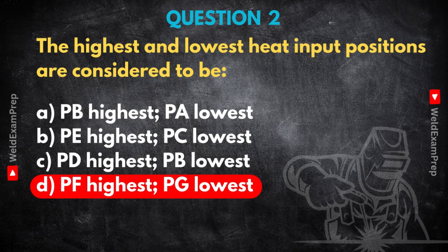For PG, the concern shifts. Lower heat input, faster travel. The risk of moving too quickly and not getting proper penetration or fusion becomes more prominent. So they'll scrutinize the weld profile, maybe pay extra attention to the root, look for signs of cold lap. Knowing PF versus PG helps them anticipate and prioritize. That's a really practical application of understanding the positions.